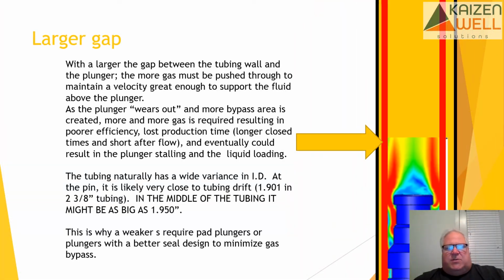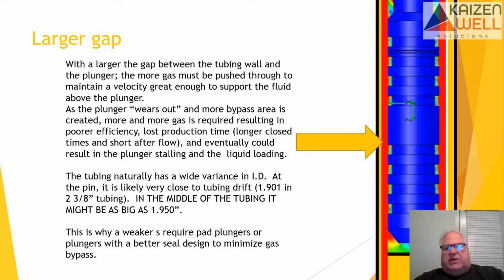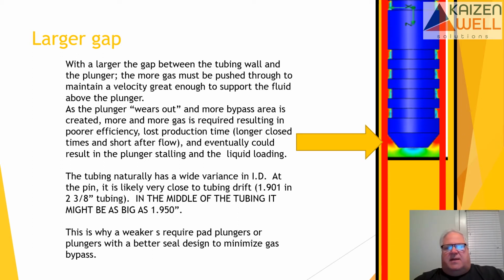Asked all the time, when do we replace the plunger? And everybody wants to know what is the wear? Do we replace it at 20 thou? Do we replace it at 30 thou? Or what? Well, the simple answer is that a plunger should be replaced when it impacts your production. And anybody that tells you you should do it at 20 thou, it's not being honest. You should replace the plunger when it impacts production.